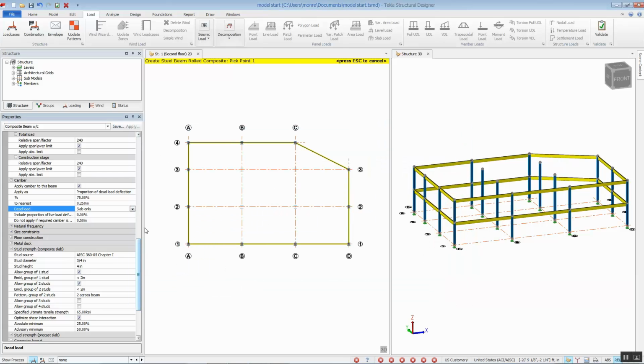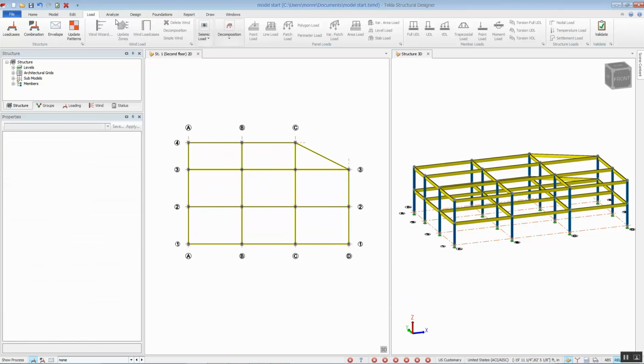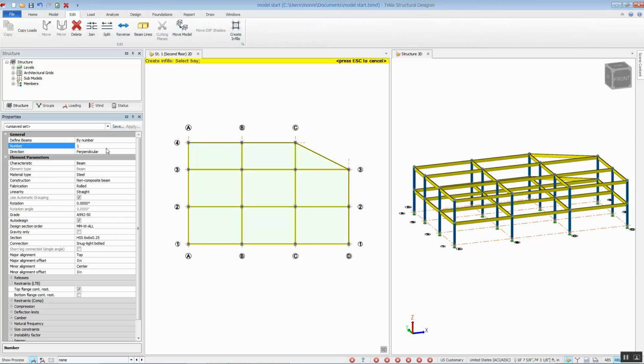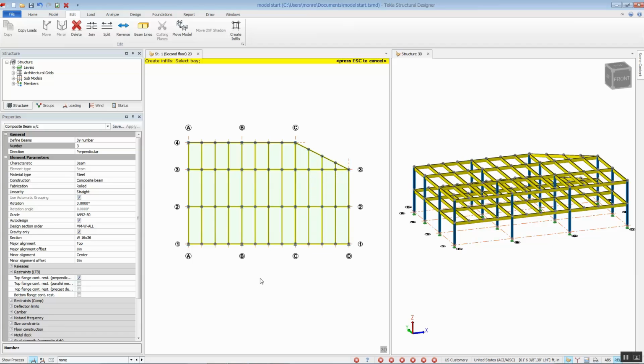I'll use this property set to generate the rest of the beams. This is accomplished quickly by drawing a window around all columns. Then, using the infill beam command, we can quickly place 3 evenly spaced beams using our pre-saved property set and placing them in every bay.